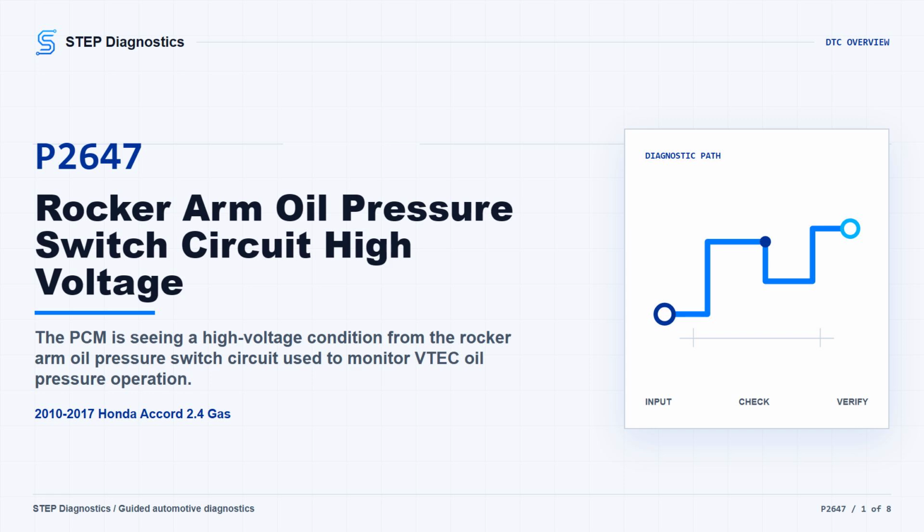Broadly, the possible fault areas include oil level, the rocker arm oil pressure switch, signal or ground wiring, connector terminal condition, and PCM-side checks after the circuit tests pass. Before testing, save the captured operating data and any onboard snapshot. If related rocker arm oil pressure codes are stored alongside P2647, check what they mean first, then come back and recheck this code.